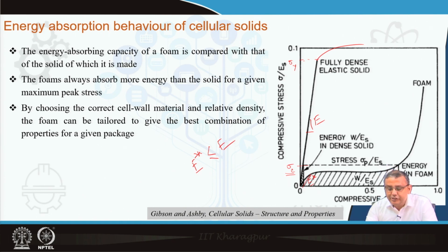But after this initial value, we know that this is the most important property of the foams: as we continue the deformation, the stress remains more or less constant. So, in practice we have learned that the stress typically rises continuously, but the rate of the rise is pretty slow, and if the density of the foam is very low, then we can expect this plateau region to be very long, typically up to 70 to 80% deformation.